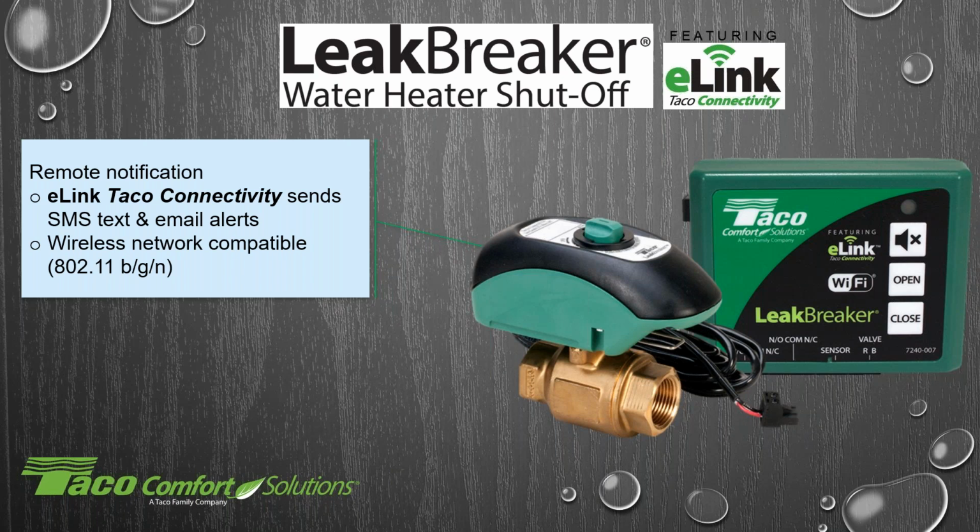So if you happen to have a larger pipe in the home as your supply, could you put this on 1 inch pipe and still safely satisfy the home's needs? I think you could. I think you could go up to 1.5 inches probably with a CV of 32. Right, because all our fixtures are low flow anyway.